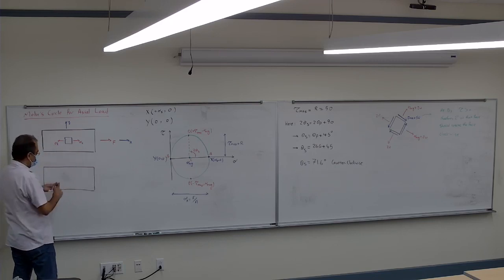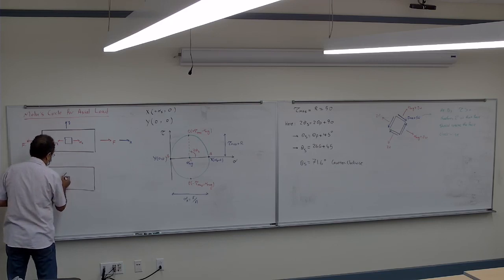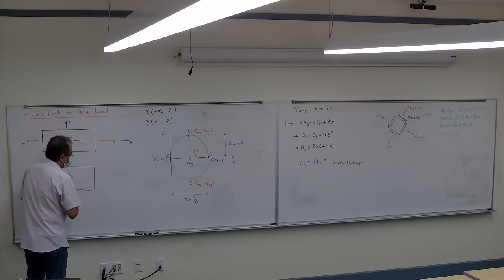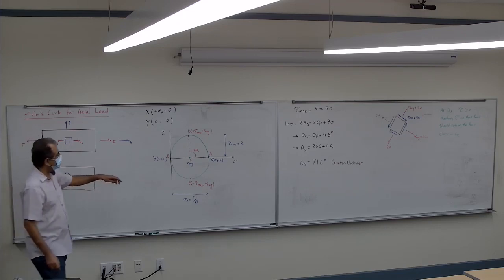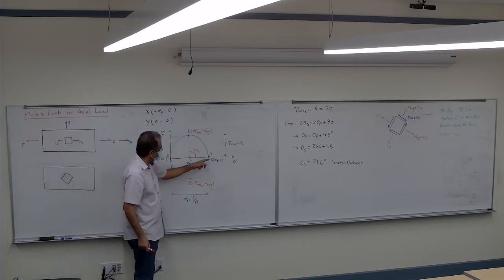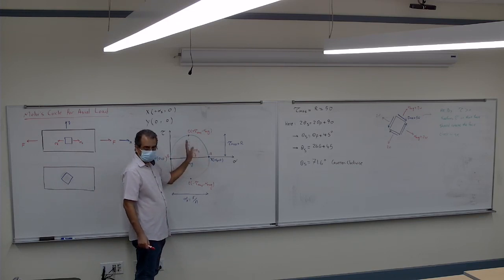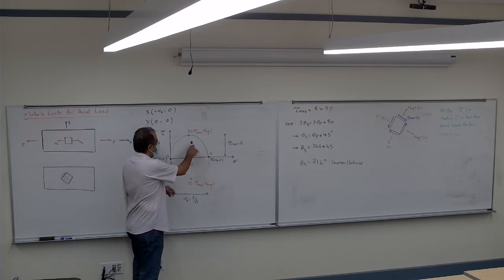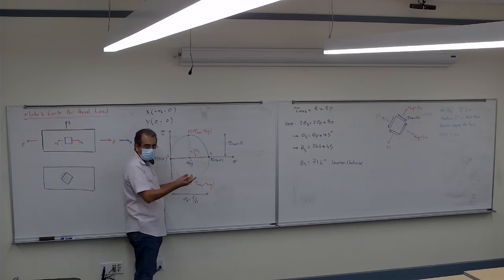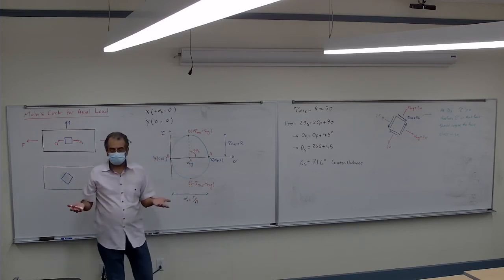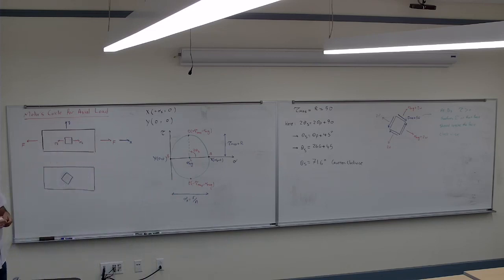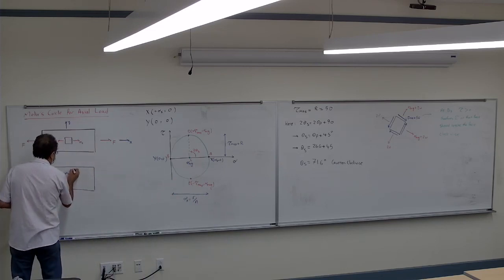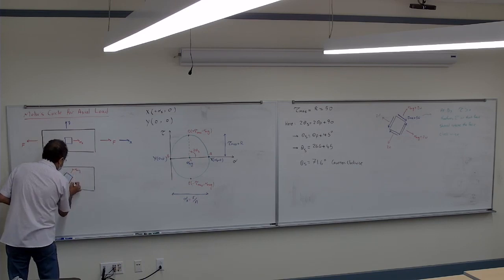If I rotate that 45 degrees, what would happen? You're not going to have shear force as well. So if I rotate it 45 degrees here, it means that I have to go from X to D. I rotate 90 degrees. 45 degrees there means 90 degrees here. If I rotate 90 degrees, the sigma would be sigma average on all faces, correct? So I would have the sigma average on all faces.